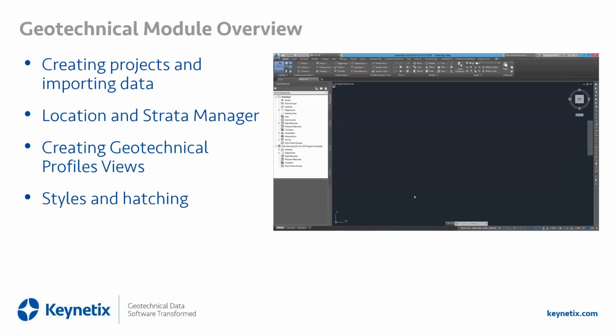The main elements, which I'll quickly show you, are the ability to create geotechnical projects on your local machine, import the geotechnical data, and then by using the location manager or the strata manager, visualize individual borings or boreholes. You will hear me jump from borings to boreholes. In the UK, we call them boreholes. In the US, you primarily call them borings. So you'll be able to generate 3D borings.